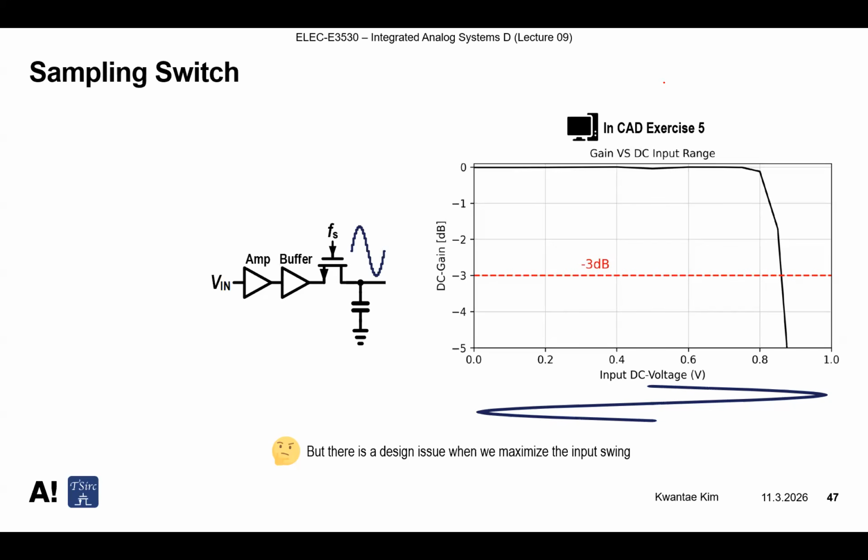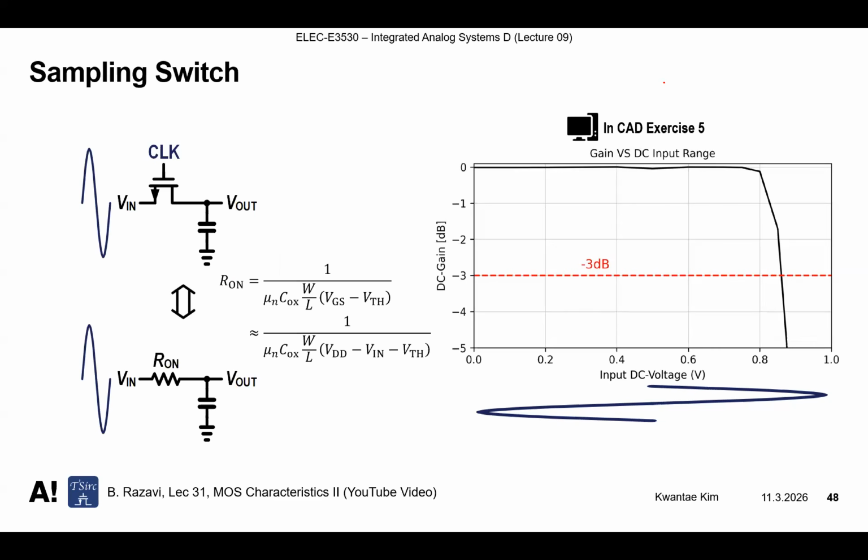This is the problem, because this part experiences low gain, which leads to signal distortion. For the peak of this signal, within the low gain part, it squeezes out to a little bit lower gain. And for the lower-voltage part, it experiences a DC gain equal to 1. So this is a problem.